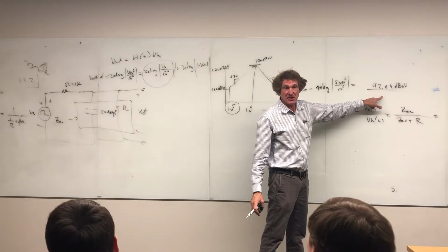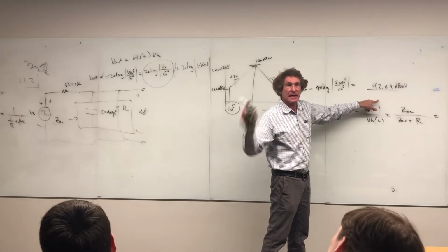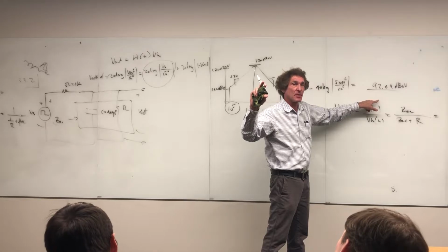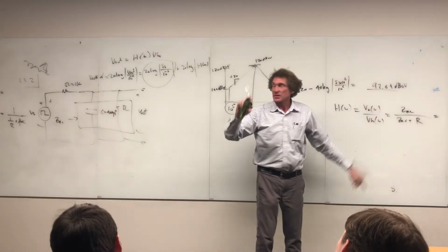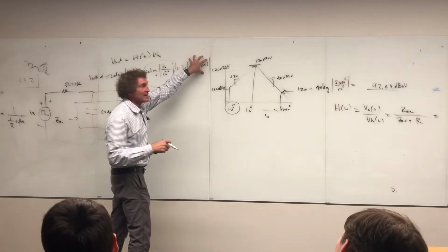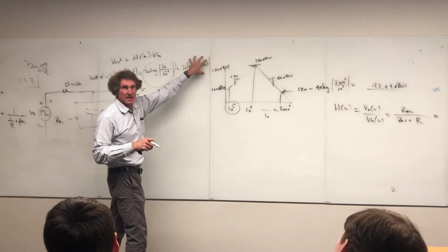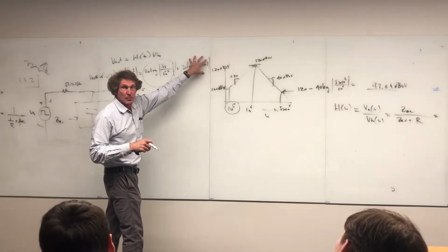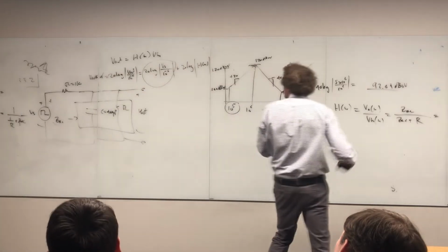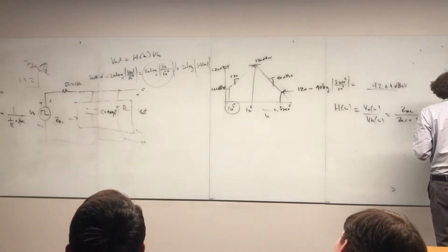That is the signal, the 50th harmonic. If you look at the input clock, that's what the value of that 50th harmonic is, right? So the only thing we need to do, we put that value in here, we have to evaluate that at omega's 50 or 5 times 10 to the 6th, really, right? Correct, class? Now you got to put the right frequency in. So when we do that, let me go ahead and just do this right here.